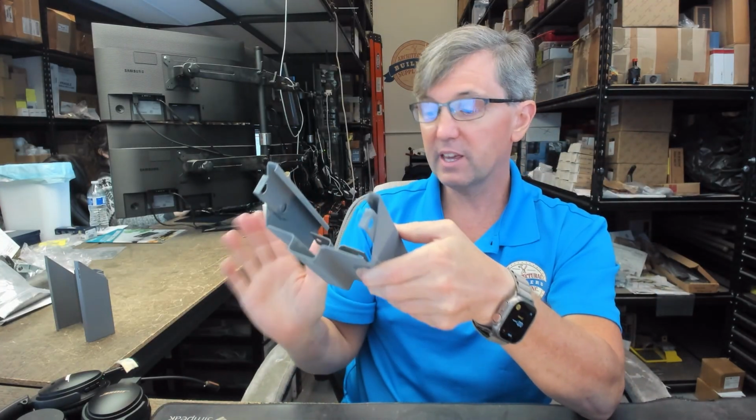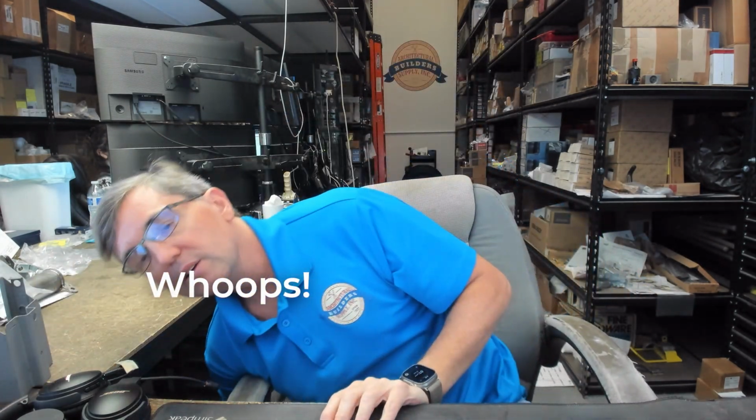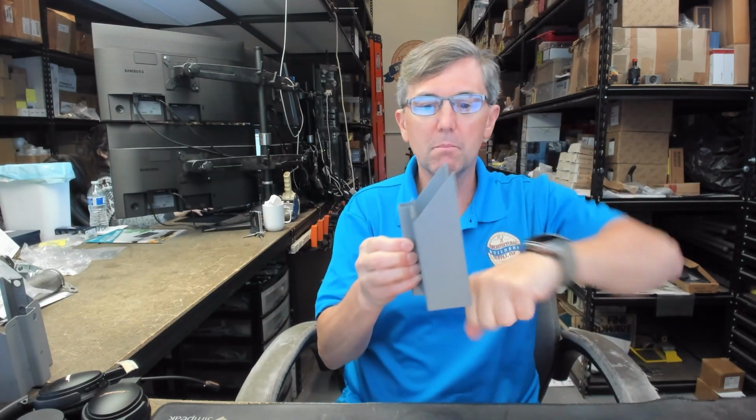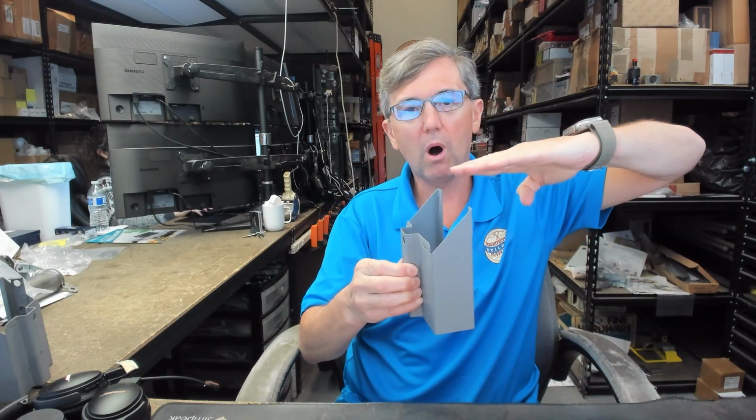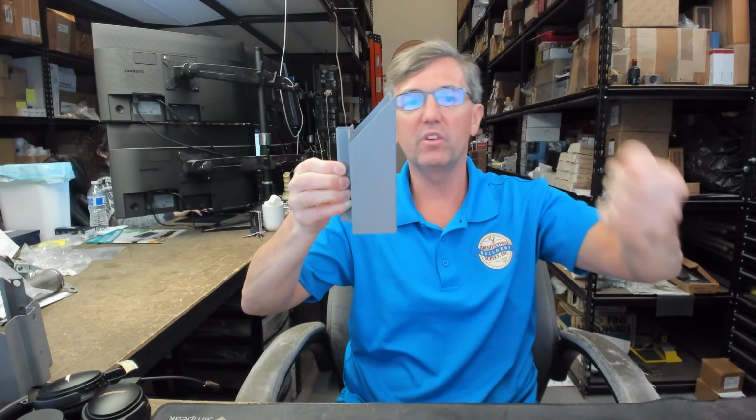Another, and again, in no particular order, an inherent design element of drywall frames is that they don't have dust boxes or mortar boxes or mortar guards over the hinge and hard strike and other hardware reinforcements. When you're doing a knockdown drywall frame, interior partition work, you don't necessarily need to have mortar guards over the back of your hinge plates, because you're not going to be sloshing mortar in the back of the jamb as you build the wall up. As you build the wall up, you're not going to be backfilling it with mortar.